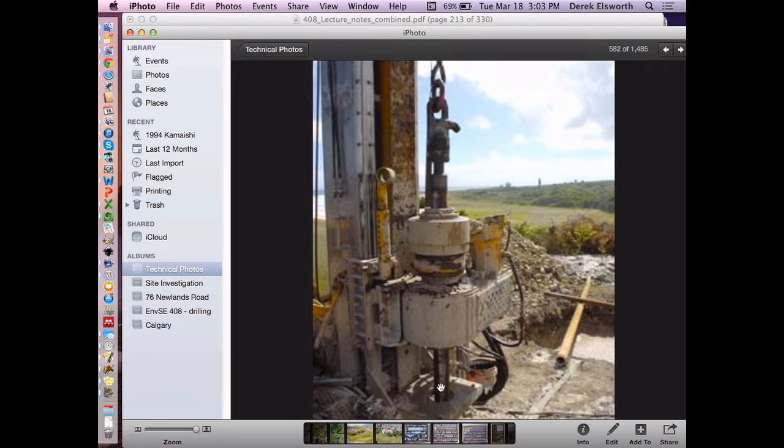Once it gets to the bottom of the run, you uncouple this hose, you pull another piece of drill steel up into the mast, which is what that boom is for. You screw it down onto the one that's before it, and then you attach the fluid injection part that circulates water into it to the top, and then you just keep on drilling.